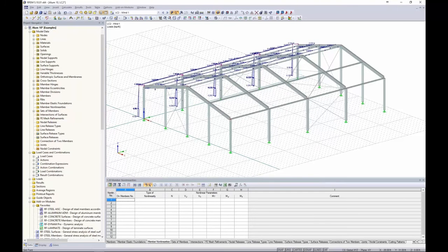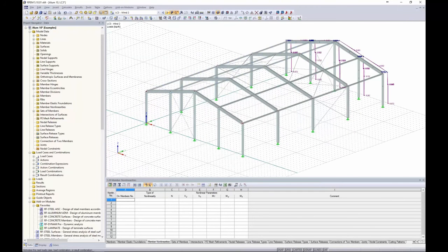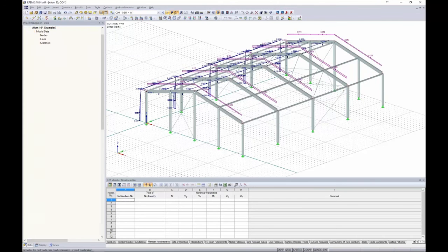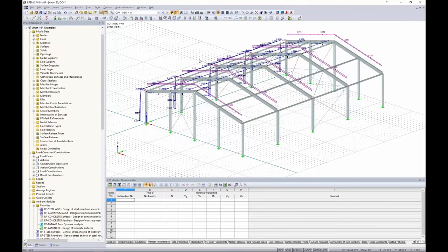Now you can see those wind loads applied for LC2 and LC3. We can always right-click to group those together as an area load as well if we want to make it a little bit of a cleaner look. So realistically, we are done loading the structure. You can scroll through to these different load combinations and see how both dead load and the wind loads will be applied, including the load factors.